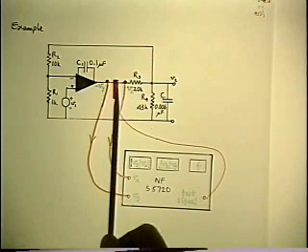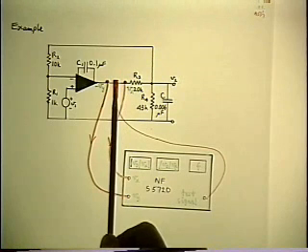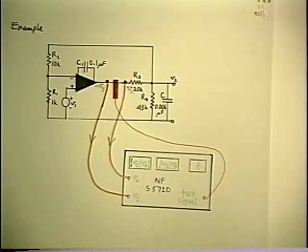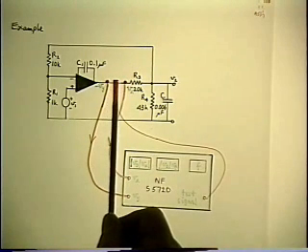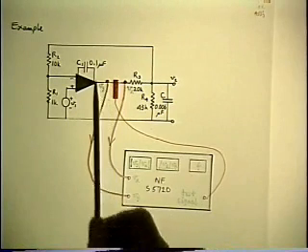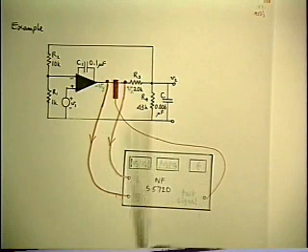Now, certainly the probe response drops off pretty drastically towards low frequencies. In fact, it starts dropping off at several hundred hertz. It doesn't matter as long as you can inject enough to see the signal. And even if you run out of signal amplitude, there's plenty of room inside that probe to wrap that wire around it 10 times. And you make a 10-turn secondary injection transformer and you get 20 dB more signal. So you can extend the range quite a bit like that.